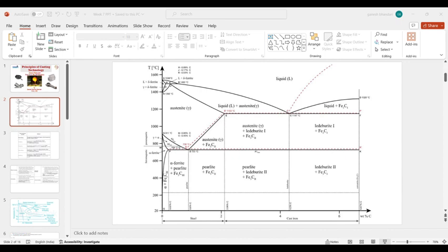If we need very high strength in our sample, then we need smaller size grains. And if we need very high hardness in our sample, then we can go with bigger size grains also. Okay. Then coming to the third one, tempering process. So in tempering process, what we are going to do, the specimen is reheated to a temperature below lower critical temperature followed by any desired rate of cooling.